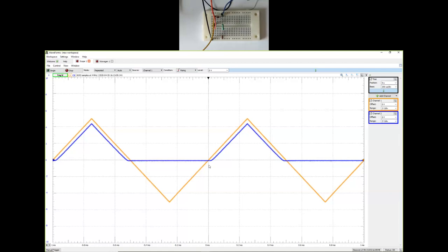And that's the first step to convert an AC signal to a DC signal. Move the average up, and then if we are able to use a smoothing capacitor, it will look more and more like a DC voltage. So that's essentially step number one.